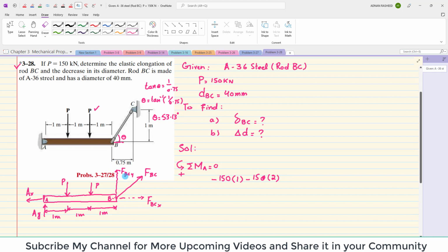The third force which produces moment is F_BC y, the vertical component, because the horizontal component passes through point A and will not produce any moment. This vertical component is equal to F_BC sine of 53.13 degree, and the perpendicular distance will be 3. Their sum must be equal to 0. When you solve this, you will get F_BC equal to 187.5 kilonewton.